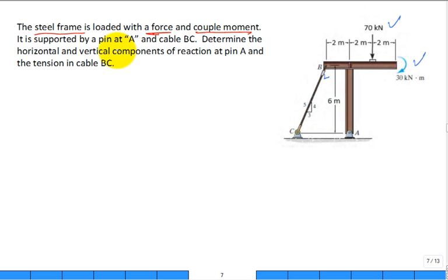It is supported by a pin at A. Now we find our location A, and we look. Does that look like a pinned support at A? Yeah, okay. So when we think about that pin, this frame could rotate and go in that position, and that support would not offer any resistance to rotation about point A. But that support would not allow that frame to either be pushed deeper into the floor or lifted off of the floor. That pin would have a lot to say about that.